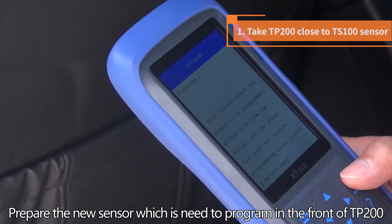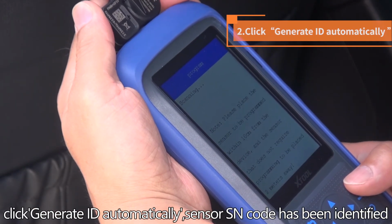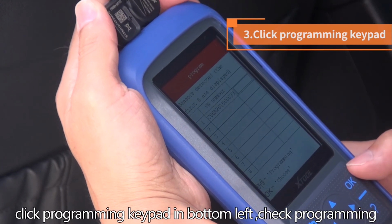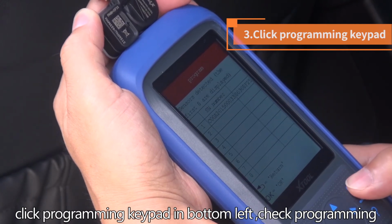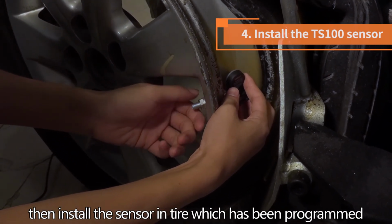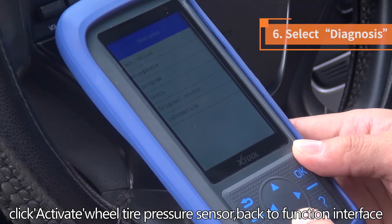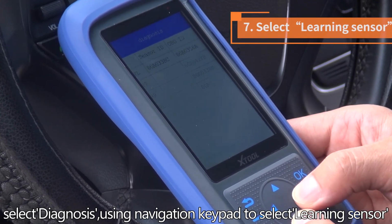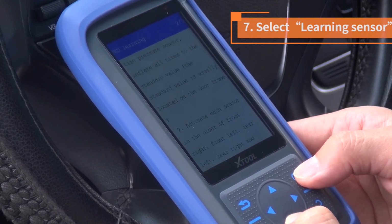Prepare the new sensor which needs to be programmed in front of TP200. Click Generate ID automatically. Sensor SN code has been identified. Click Programming keypad in bottom left. Check Programming. Then install the sensor in the tire which has been programmed. Click Activate Wheel Tire Pressure Sensor. Back to function interface, select Diagnosis, using navigation keypad to select Learning Sensor, view the hint to learn sensor.